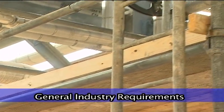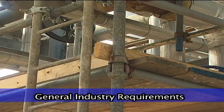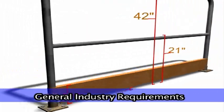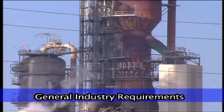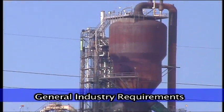Wherever there is the risk of tools, machine parts, or equipment falling to a lower level, toe boards must be provided. Toe boards should be 4 inches high, with no more than 1/4 inch clearance above the floor. Regardless of height, all open-sided floors, walkways, platforms and/or runways above or adjacent to dangerous equipment must be guarded with a standard railing and toe board.